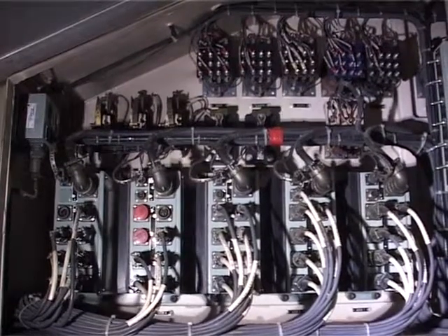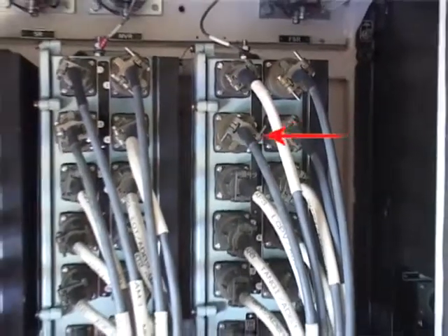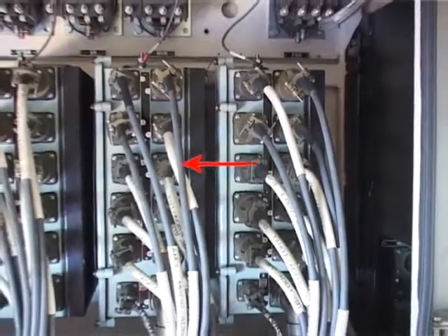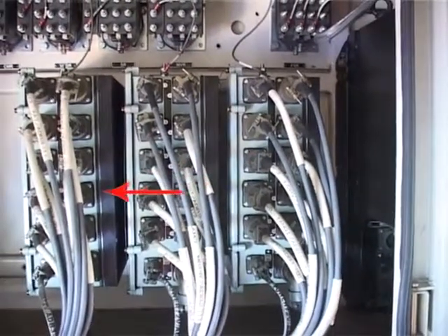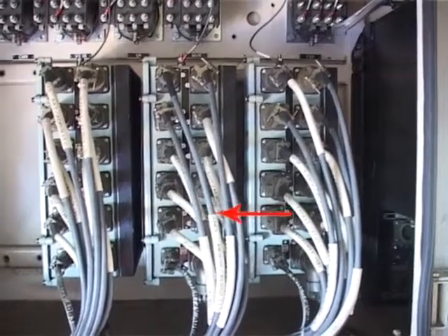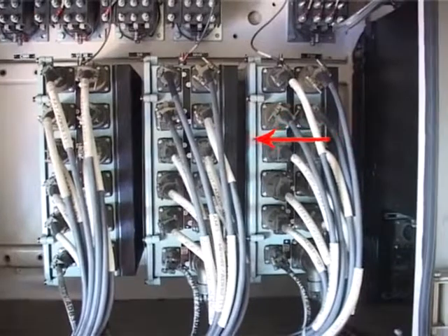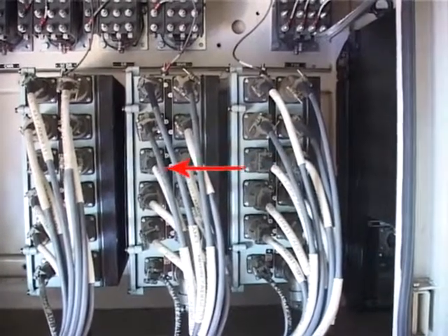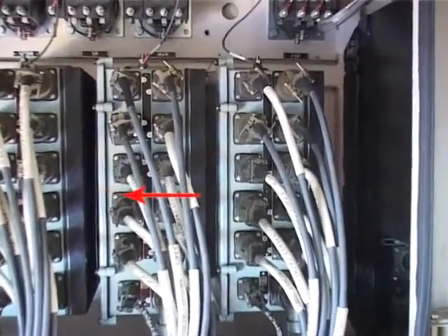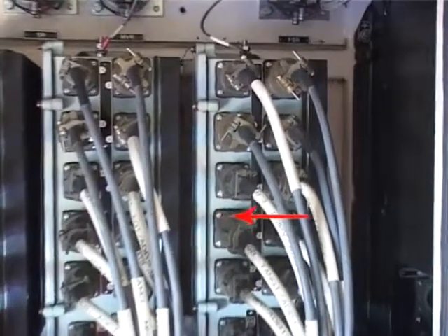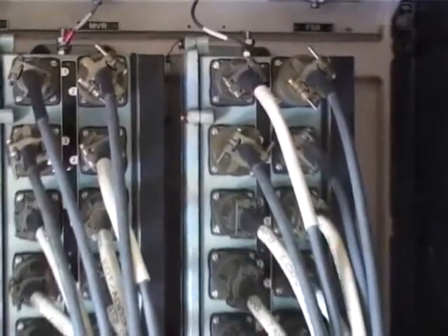Analog distribution box ADB, MDB701. The analog distribution box provides regulated DC power to various sensors that are connected to the ADB. It also collects output signals from these sensors and transmits them to the main control unit. There are 4 ADBs per loco.